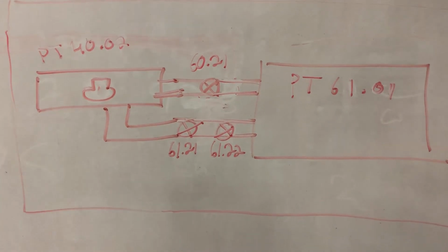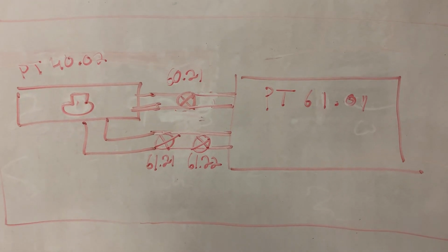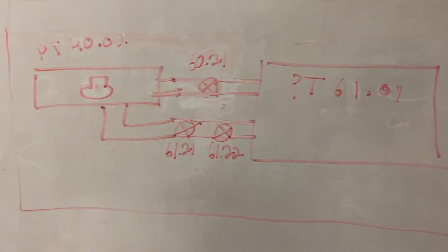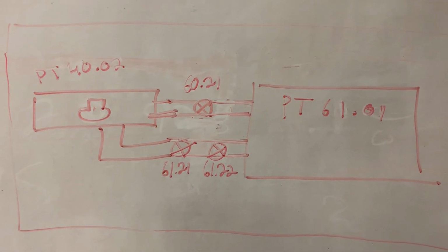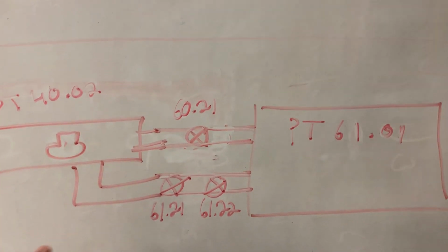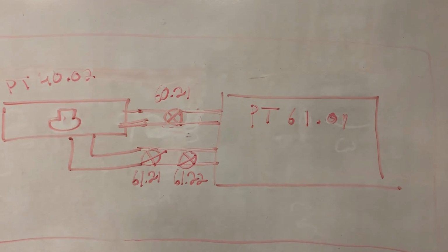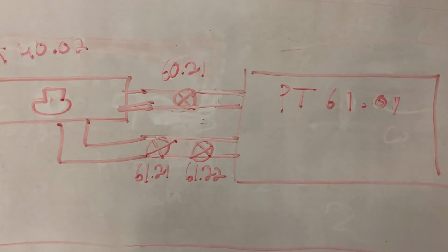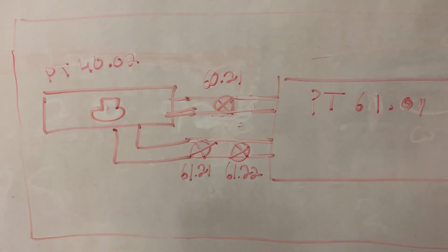Right now, what's happening is you're flowing liquid nitrogen out to the chamber. It's going to exchange heat with the shrouds, and then gas is going to come back. So the pressure is going to build up to the point where once the pressure in the dewar gets to about 10 bar, the pump turns off. So once we hit 10 bar, we're going to go ahead and set the system into idle mode,